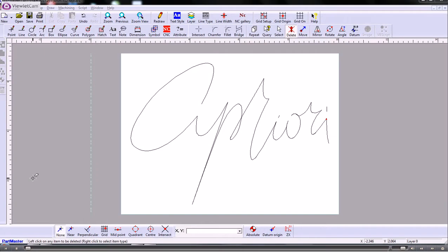Okay, this video shows you how we can import this little file. It is imported using DXF release 12. It has to be release 12 because other versions of the DXF interface use NURBS, which we can't read in. NURBS are just a particular mathematical formula for describing curves. So we need arcs and lines, and you can get that using release 12.